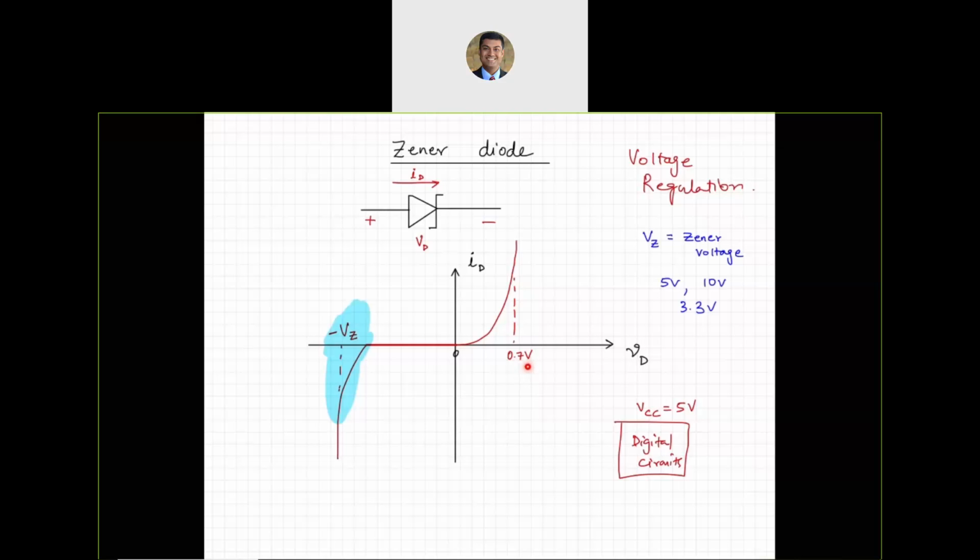So instead, you use one diode, but in the reverse breakdown region to give you that voltage regulation, which is why Zener diode is useful here. You could also do it with the normal diode in the forward biased region, but you'll have to put a few together depending on what voltage you need to reach, and that is essentially the limiting factor here.